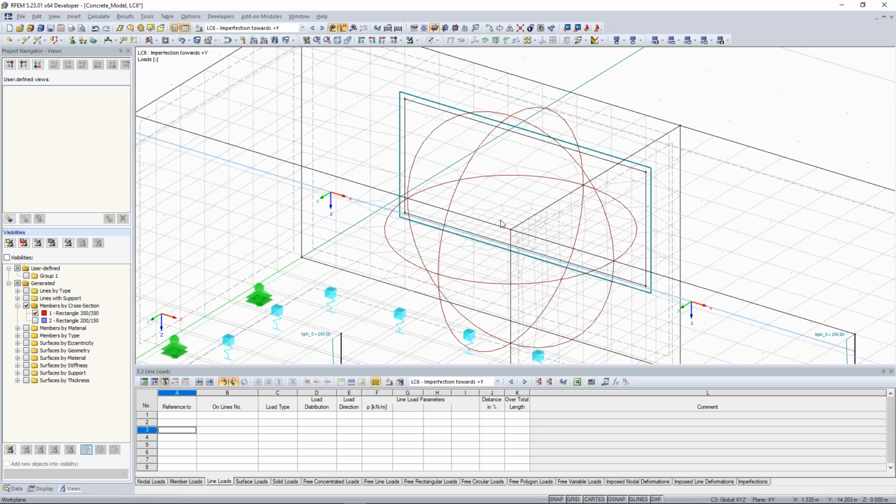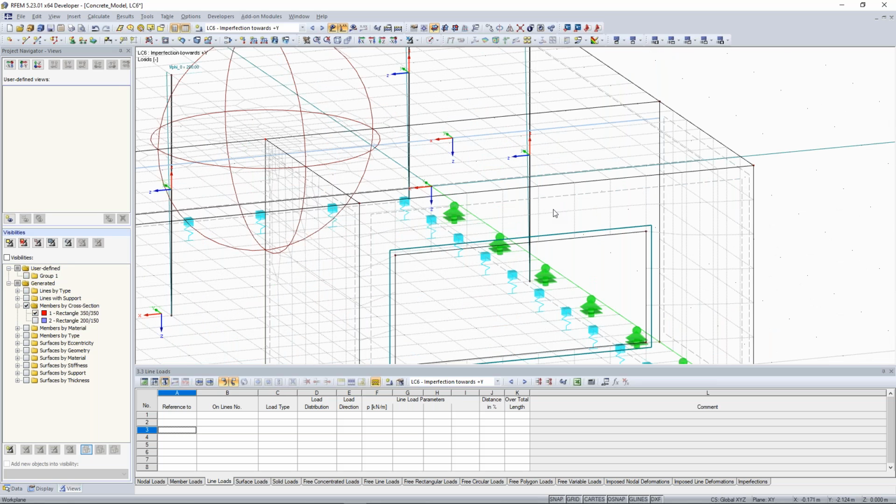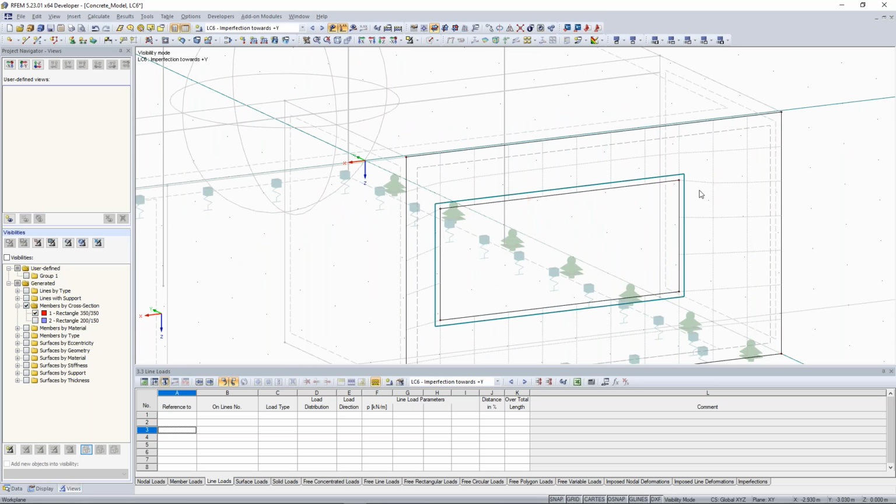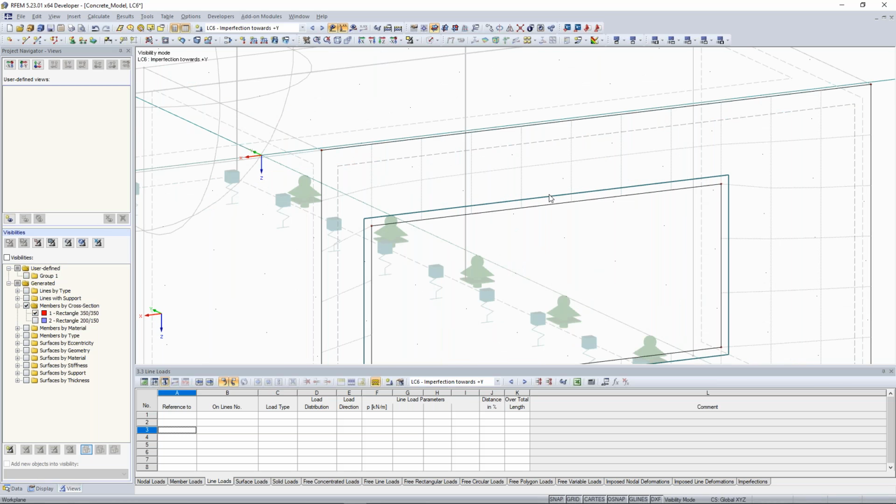It's up to you how to do that. For example, I learned that at least here you need 4 FE elements in order to have good results at this surface. So when you want to interpret some internal forces or some results, I don't know if 2 FE elements are enough in order to get good results.